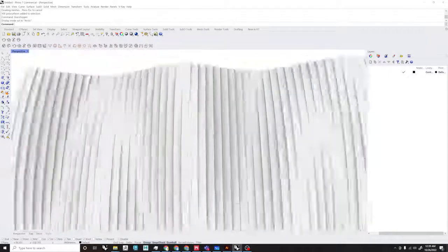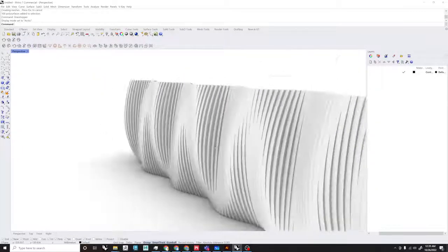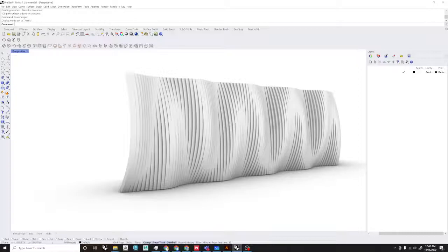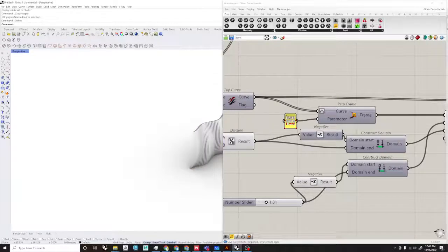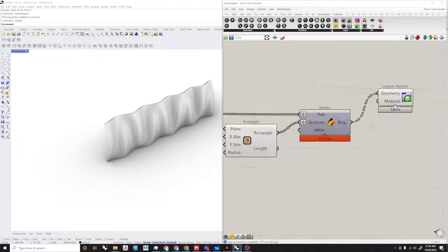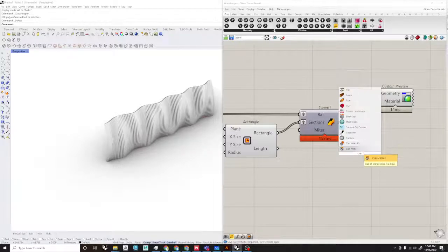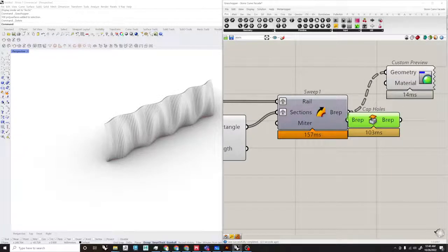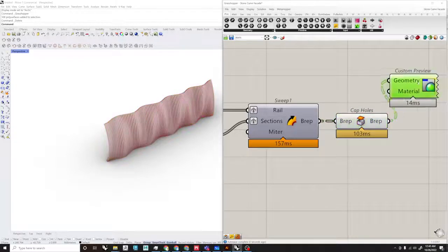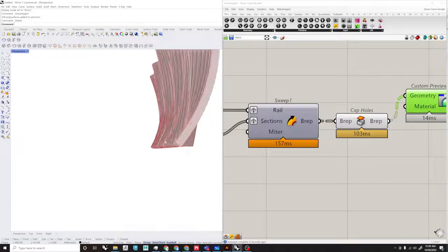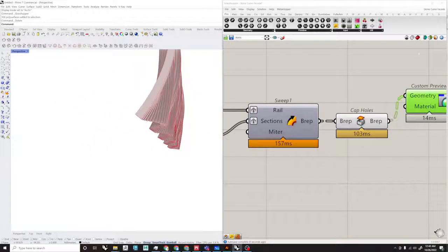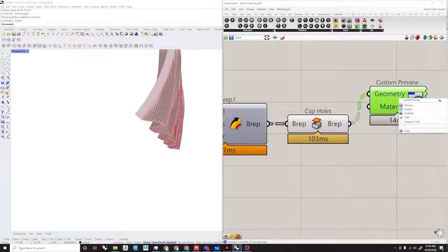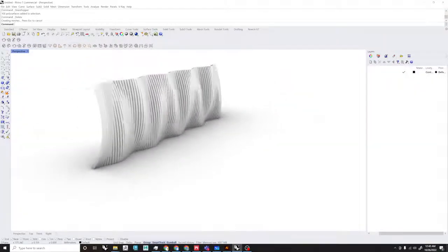The other thing I forgot to do as well in Grasshopper is cap it. So use a cap. Now you can see that these curves are a little exaggerated too. You can see that it's not perfectly flat either. So normally I would do that in Rhino. I wouldn't waste my time doing that in Grasshopper because it's just a waste of time.